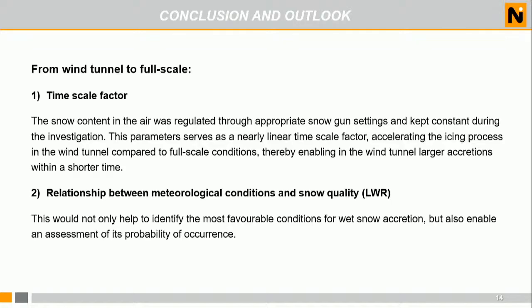First of all, there is a time scale factor, because in the wind tunnel we were able to test in 1 hour what we could obtain in full scale in many hours, maybe days. So we are accelerating the process, and this is just because we inject in the air a concentration of particles which is higher with respect to full scale. This scaling should be linear, according to literature.